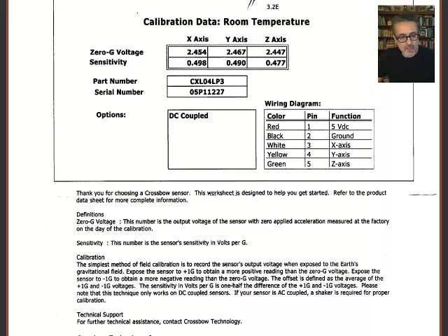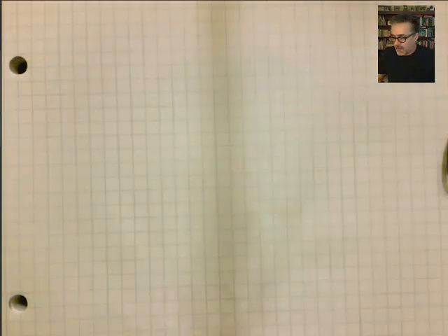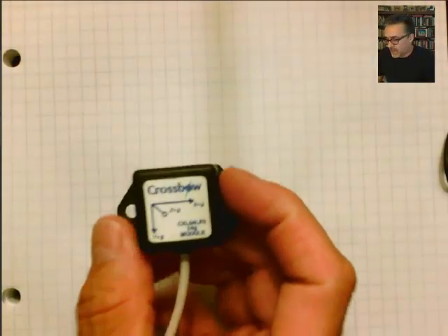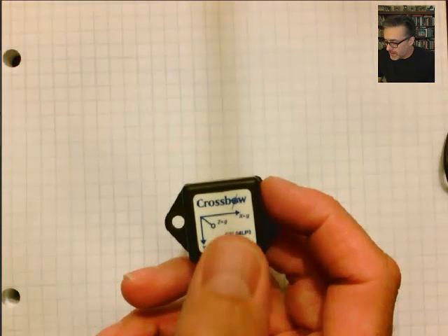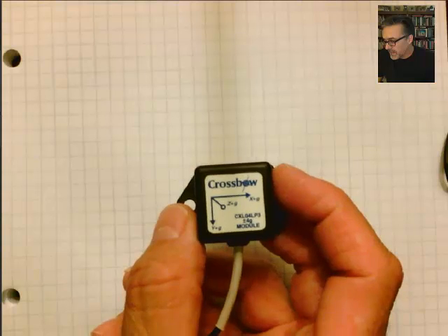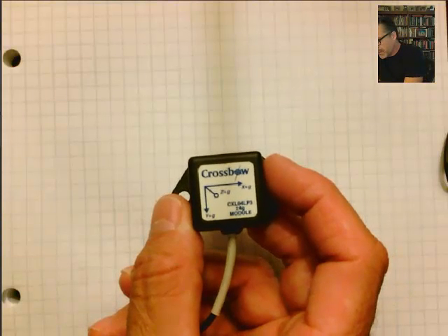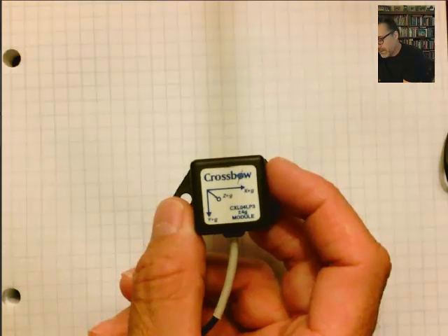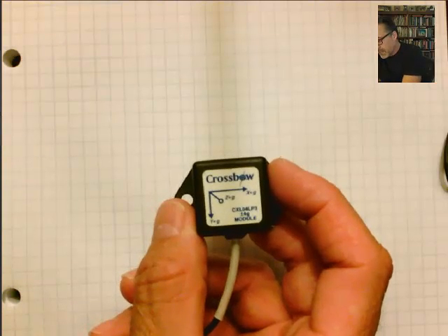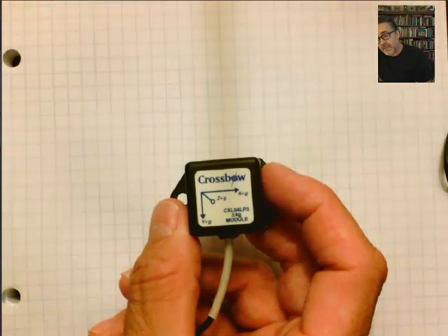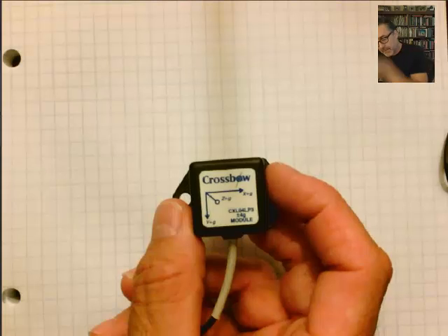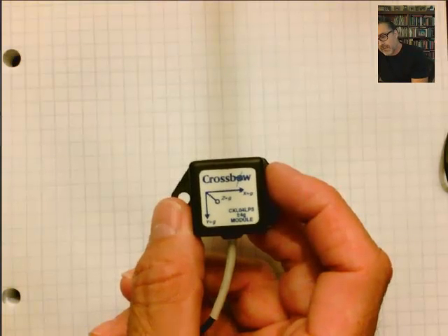The way I learned that was when I was learning to use accelerometers. So let's say, again, I have Z. The 0 means what? That it's actually positive down, right? If I had an arrow, that would mean the positive was up. So it's positive down because you're looking at it from down this way. The output from the z-axis should be reading 2.5 volts, plus, right? Positive G, so another half volt. So you would probably read 3 volts out of that, if I'm interpreting that correctly.